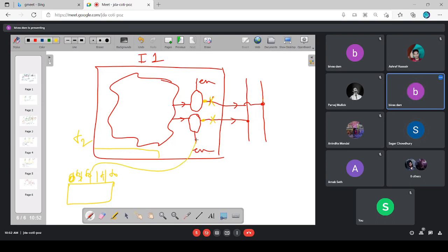Or if it is an internal decoder, from here again F2 comes here. So I decode the address and the output that I get, that output will actually go as the Z input of the tri-state logic. Z input or enable input, whatever you may term.